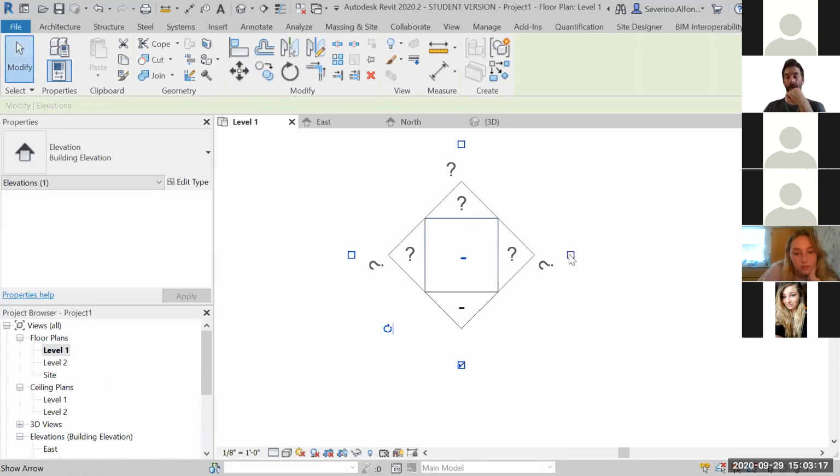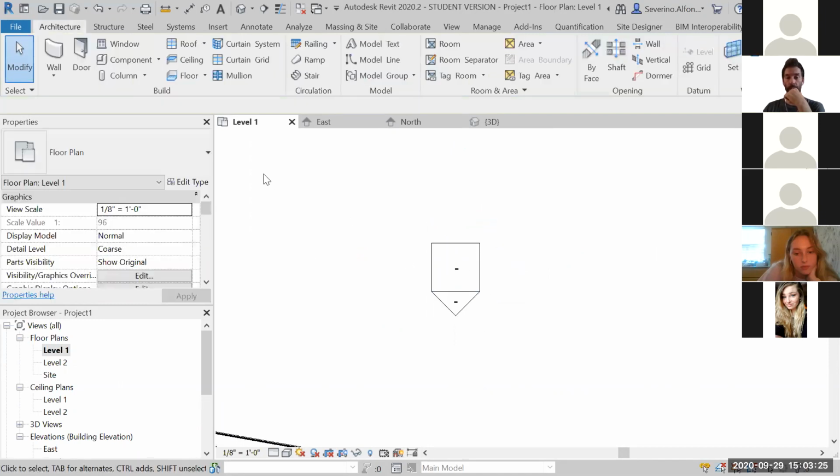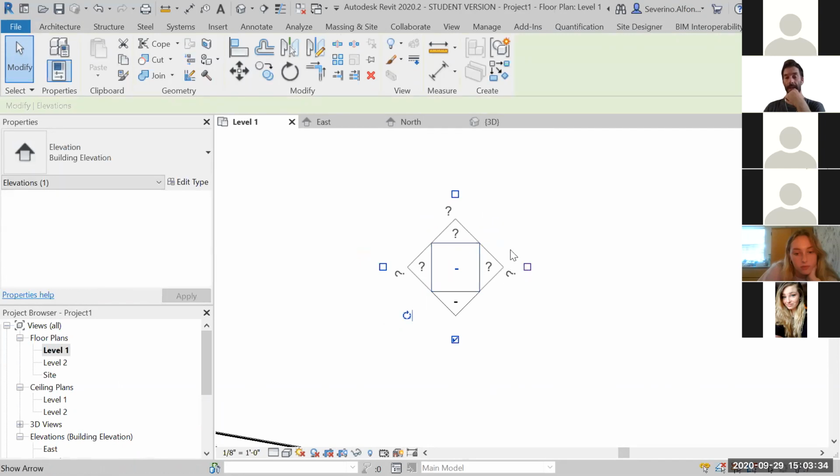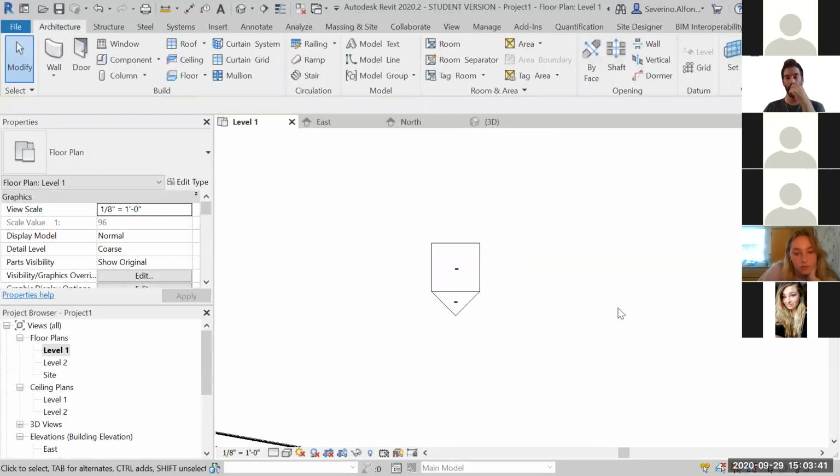And basically you can check on these 3 options if you were to have an interior elevation that looks in 4 different directions. Let's imagine you have a room, let's say an office space that is actually here. You will introduce this symbol and you will activate these other interior elevations. And you will rename them and they will appear here. Slowly, I think we will get there.